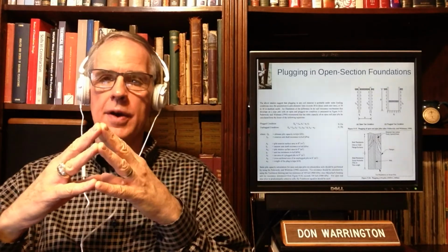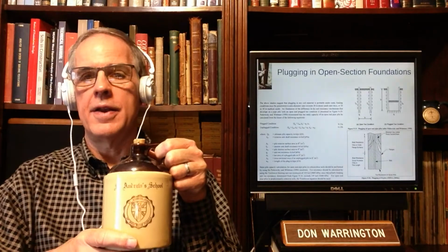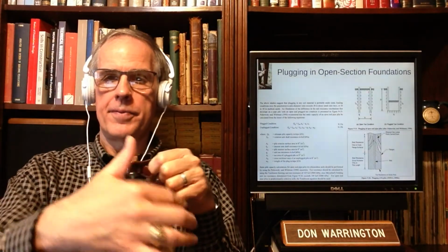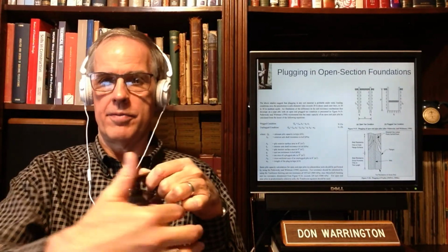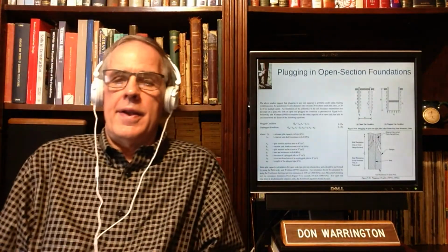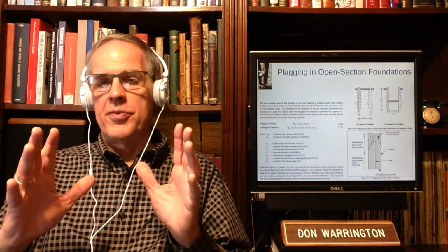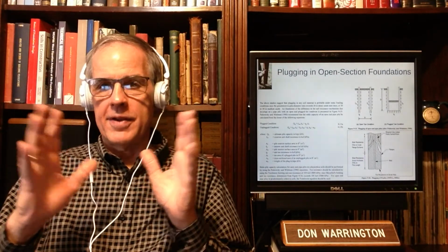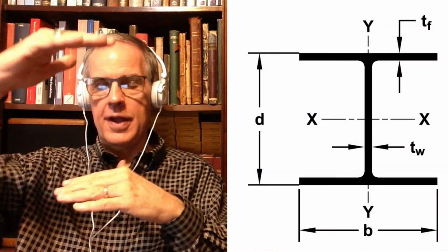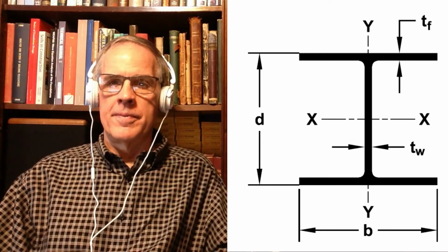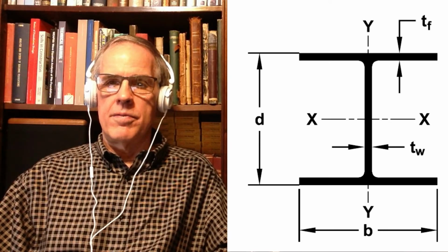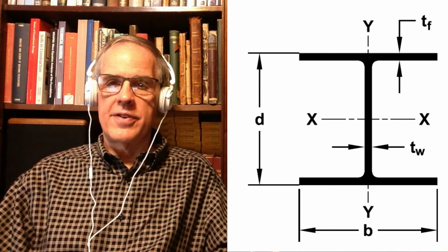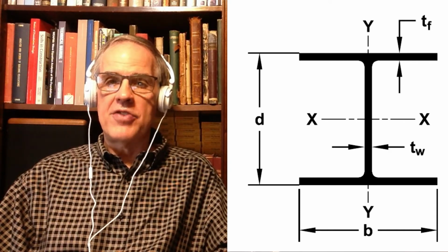When we were talking about the perimeter of the pile, it is all the way around this way. With an H-beam, the perimeter is in rough terms 6 times the basic flange width of the H, because H-beams are set up so that the flange width and the depth are basically the same. And the wetted area is 6 times that.